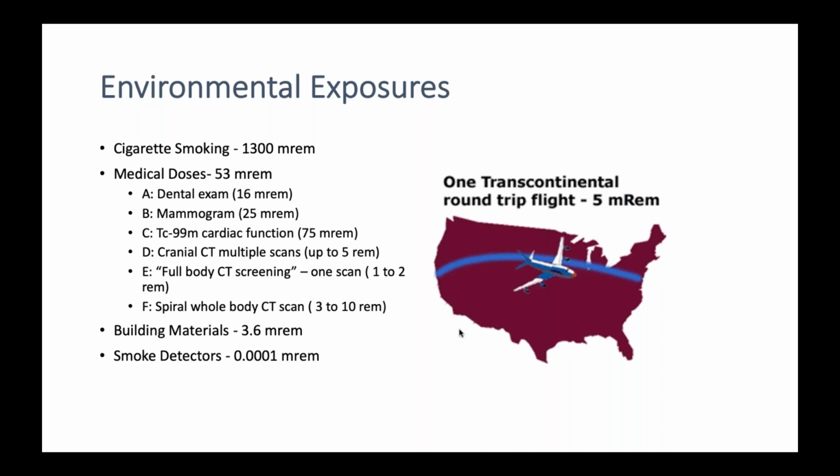That alpha emitter hits air molecules, ionizes them, and makes that space conductive. If you get smoke in there, it interferes with those alpha particles hitting the air molecules, so the conductivity goes down. So I think that's how they sense it.